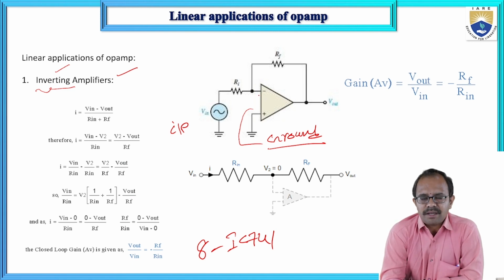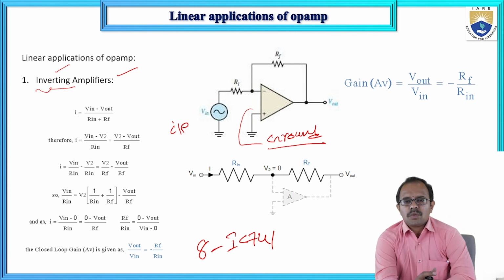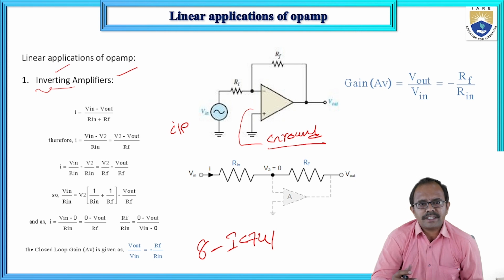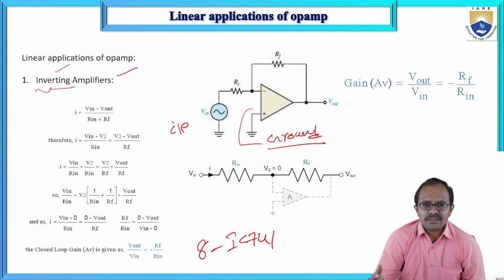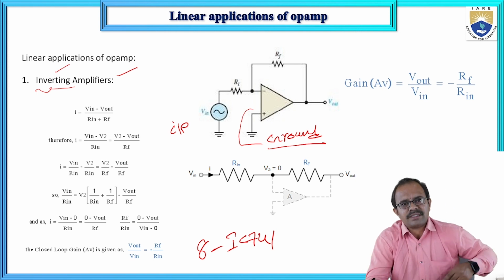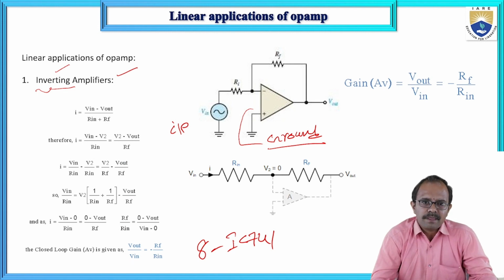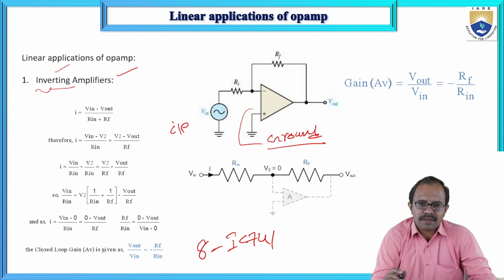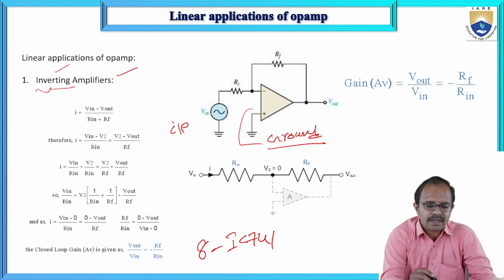IC741 or operational amplifier. And as you might be familiar, we cannot provide the input directly to the device. So that you have seen even in the transistor based amplifier. Suppose you are working with the common emitter configuration, input is provided to the base. How we are giving the source? Through some resistance. So here also we are using some resistance, so let us say RA, that is nothing but the input resistance, right?